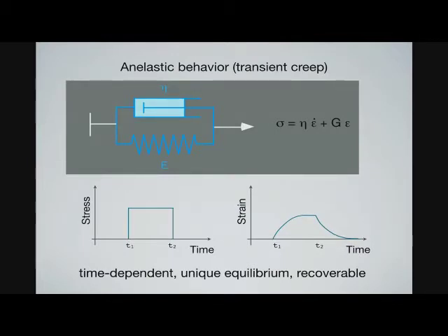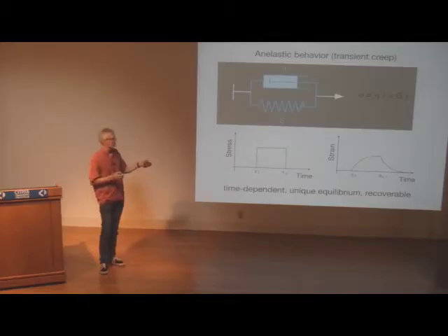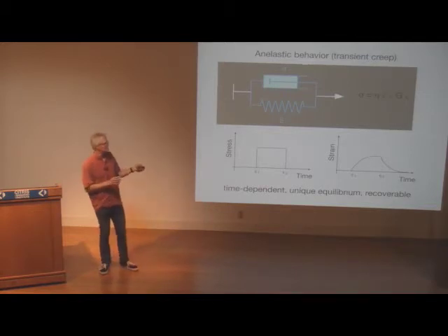And we think that springs and dashpots are nice in that sense, right? If you try to push a spoon into honey very quickly, you can't do that. You have to push it in slowly, and the more slowly you can push it in, the higher the viscosity of the honey, right? So when you combine a spring and dashpot, a spring you can deform instantaneously, right? But by this parallel connection, you can't instantaneously deform this element. There will always be a time delay because you have this viscosity of the dashpot.